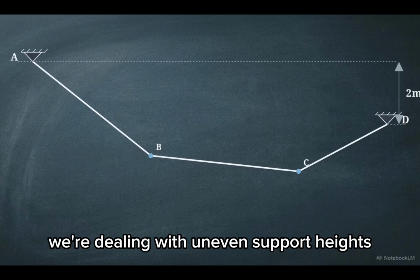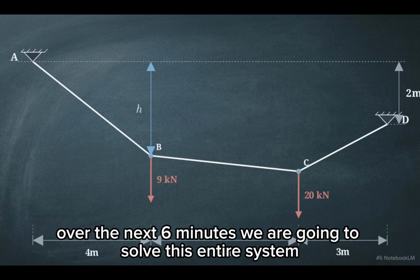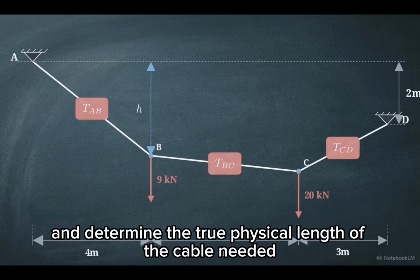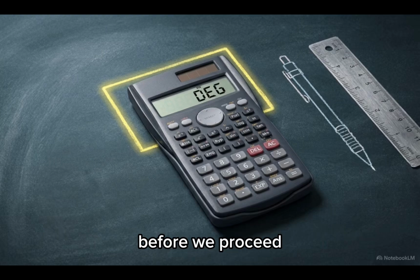We're dealing with uneven support heights, downward point loads of 9 and 20 kilonewtons, and an unknown dip height labeled here as H. Over the next 6 minutes, we are going to solve this entire system. We will calculate the exact tension in every segment, find the absolute extremes of stress, and determine the true physical length of the cable needed. Take a moment to grab your calculator and ensure your trigonometric functions are set to degrees before we proceed.